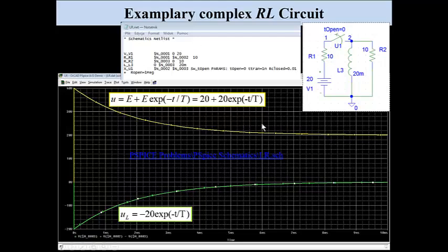At first a black window appears, then we may add traces. The first trace is the voltage across a coil, and the second trace is the voltage across the switch. We have to recall the netlist to know what the numbers of the nodes are. So this node is number 3 and this node is number 2. Number 2 is automatically assigned by schematics.